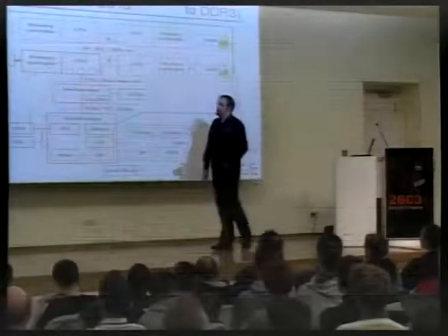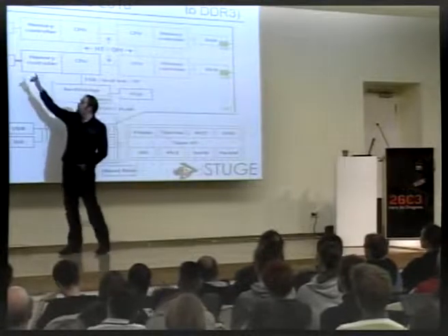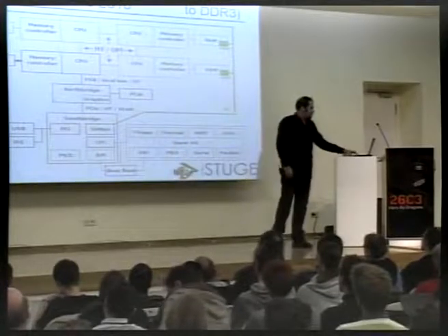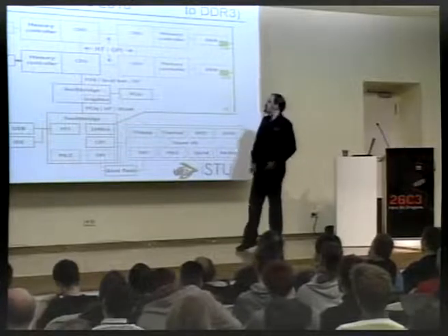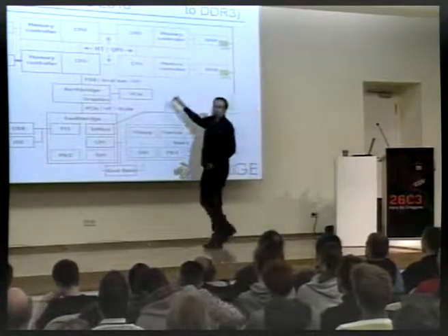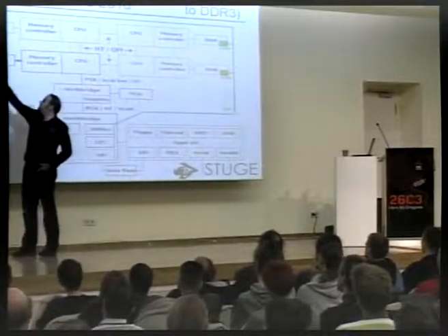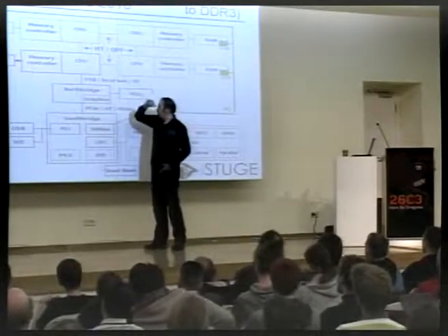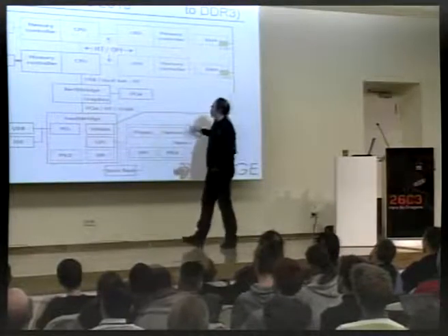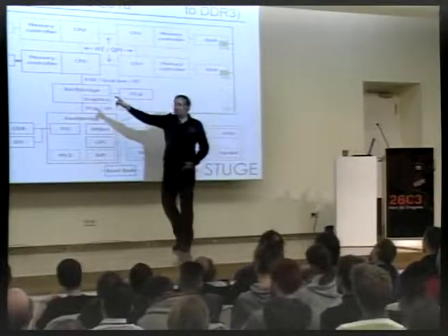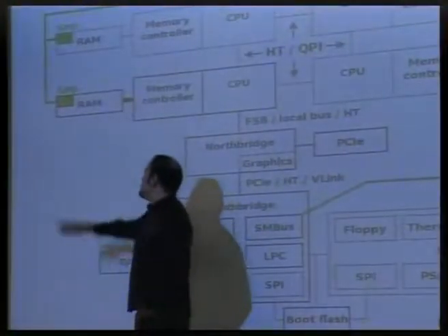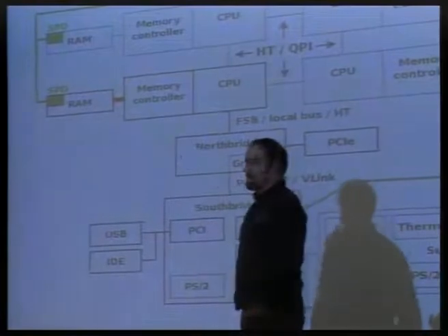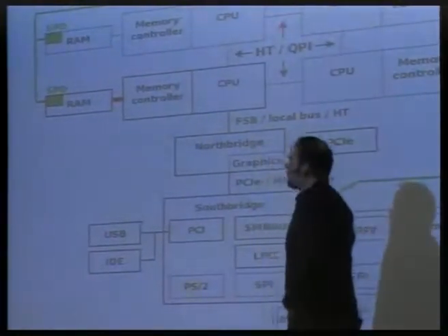And all of that configuration at this memory bus is also highly dependent on the DIMM. So where's that information stored? Well, it's stored in these green little SPD boxes on the DIMM. Of course, we're here in the boot flash, but we're running in the CPU from the boot flash, and we have to go out on this green bus and read the contents of this small little EEPROM, the SPD EEPROM, to find out how we're going to program the memory controller so that it can drive that particular RAM module on the wide red link.